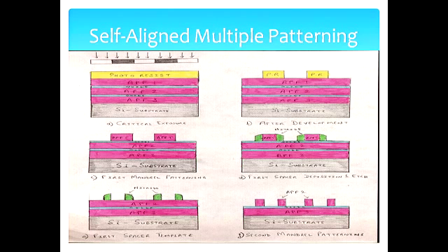How can you get the high aspect ratio, vertical? It looks like a high aspect ratio. I could be high. I don't exactly know how high you can go, but this is using RIE, reactive ion etching. You etch it away so that you get absolutely straight anisotropic structures.